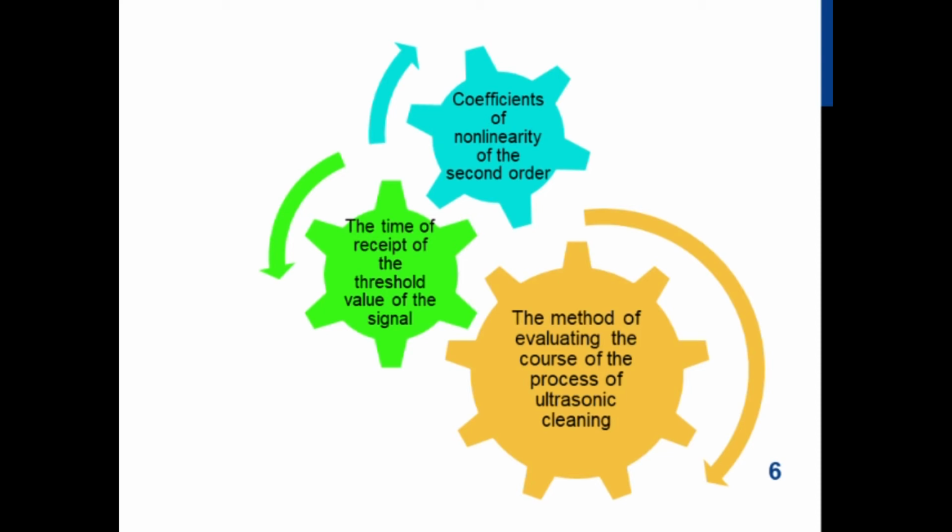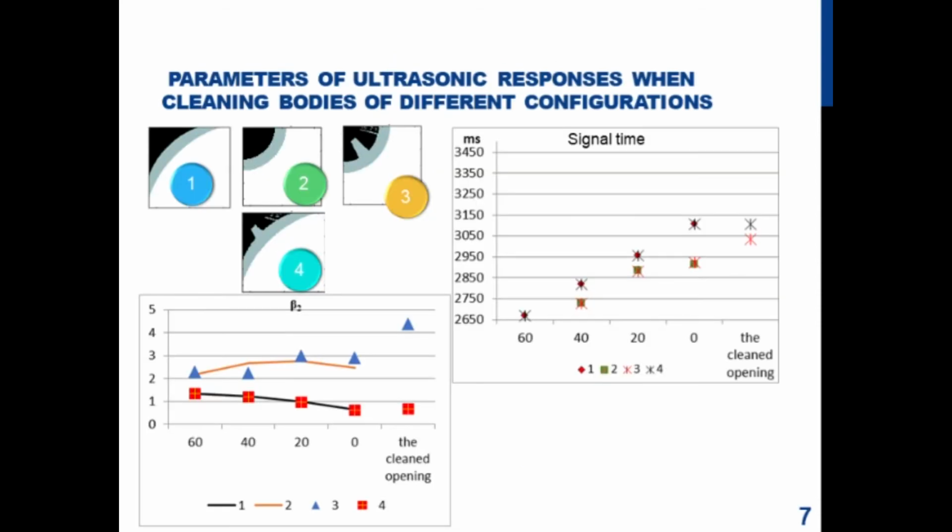Our method of evaluating the current state of ultrasonic cleaning is based on the nonlinearity coefficients and the times of receipt of the threshold value of the signal for the current and past measurements. To determine the influence of the features of the body configuration on the time of receipt of the threshold value and the nonlinearity coefficient of the second and third orders, modeling was performed for different shapes of the body, and the corresponding values were calculated.